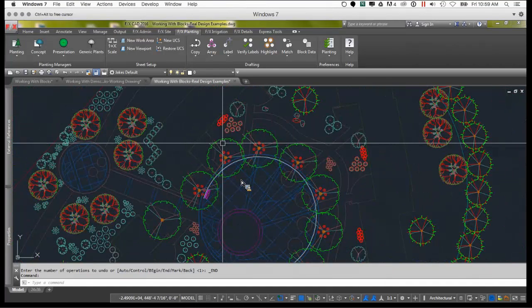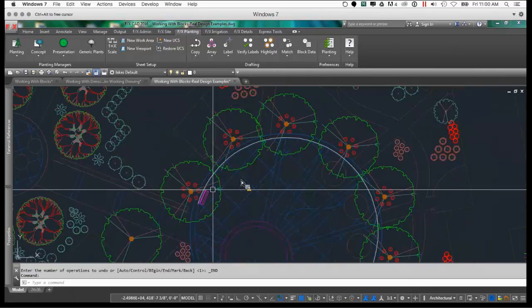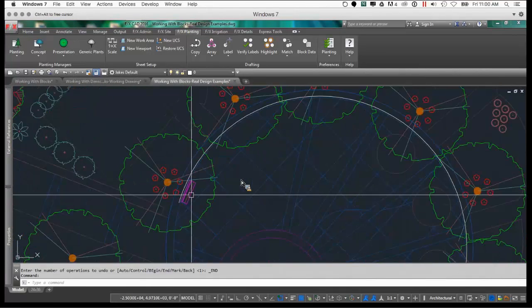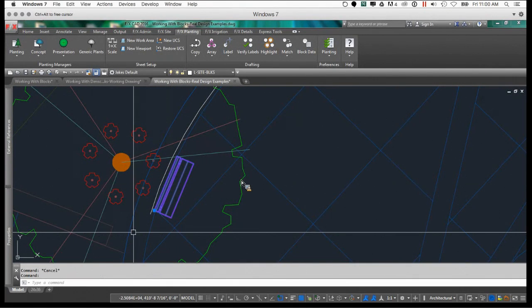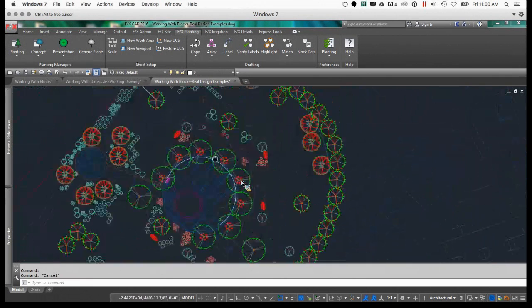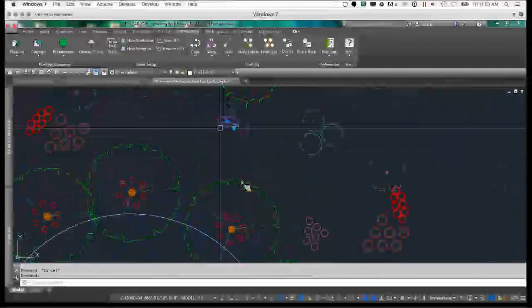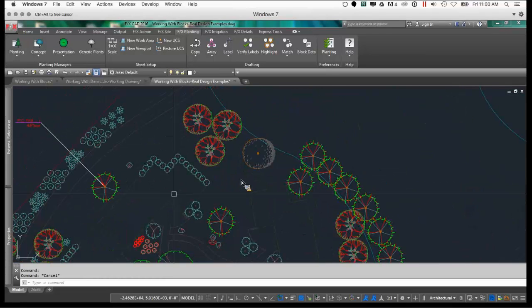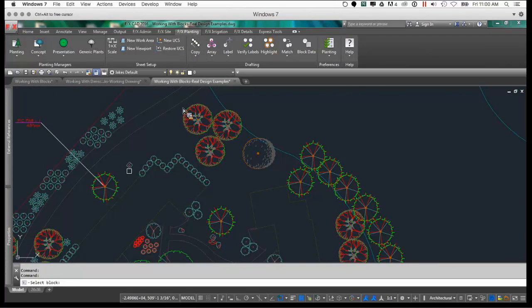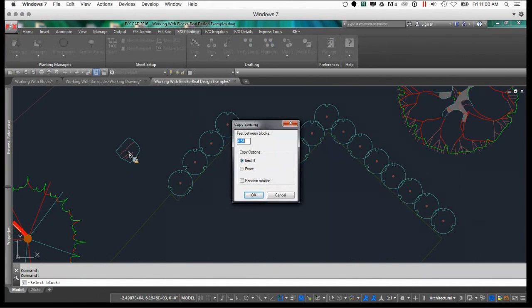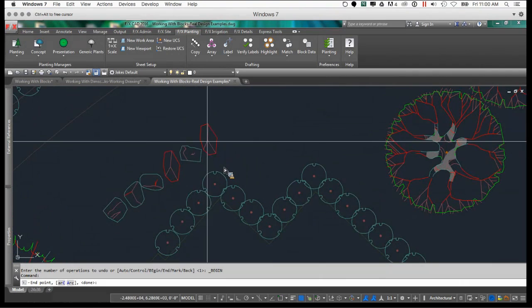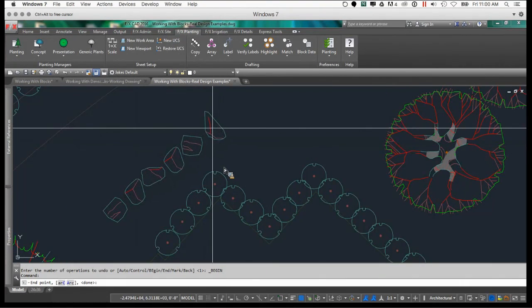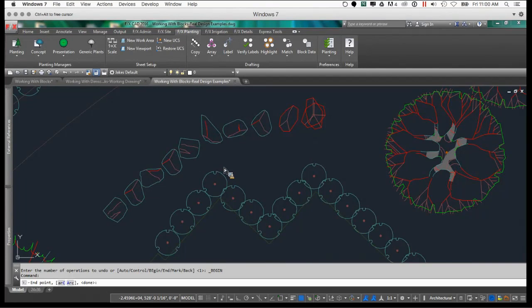They're all new blocks. They're all different blocks. But how do those actually function, what are some of those tools? Again, going to the power of using these blocks and how they actually function, we have our dynamic block in here. If we want to copy this along a line, since that is dynamic, it pulls all instances of that block and we can randomly rotate it, and it puts them in at random spots so that it doesn't ever look the same. So we can go ahead and make a rock wall.